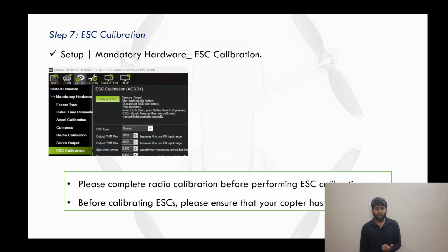Always ensure that the radio calibration is completed before initiating ESC calibration. By carefully following these steps, you will effectively calibrate the electronic speed controller, ensuring synchronized and accurate motor response for optimal flight performance.